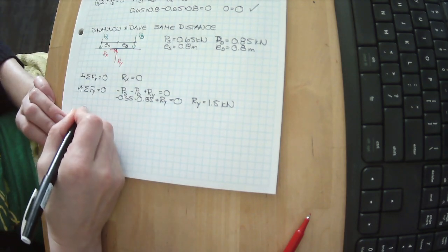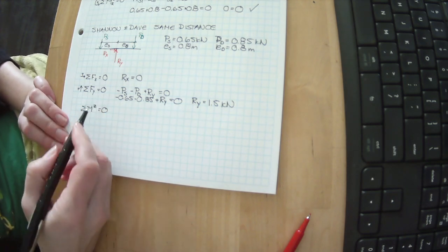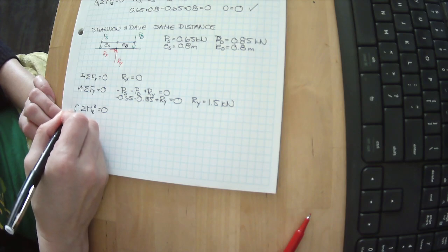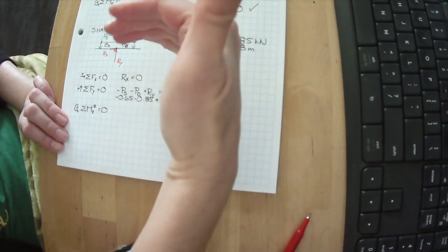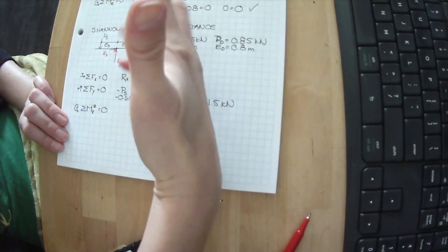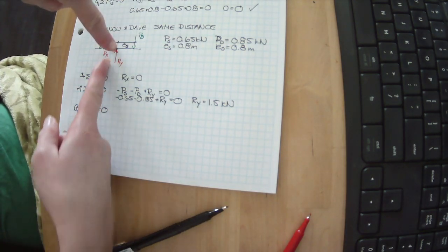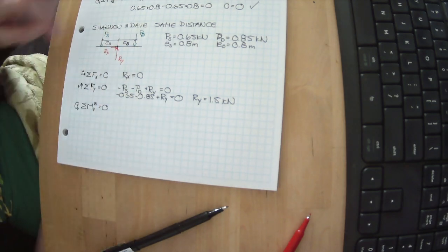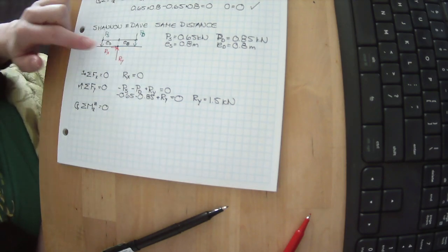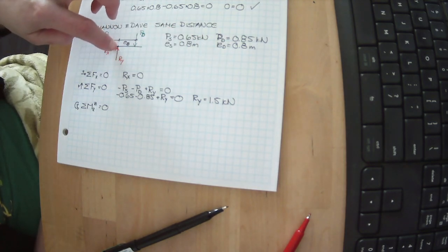So we want to sum the moments about the z-axis, and we want to see if it's all in equilibrium or not. Let's pick this point right here, where our reaction is, and let's just remind ourselves that everything spinning in that direction, or with a vector pointing out of the page, would be in the positive direction. Okay, we're putting our thumbtack right here. Our y passes right through the object, or through our pin, so it does not cause our teeter-totter to spin. Our x passes right through the spot we're talking about. It does not cause it to spin about that point.